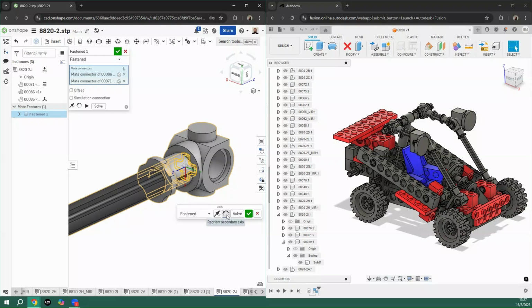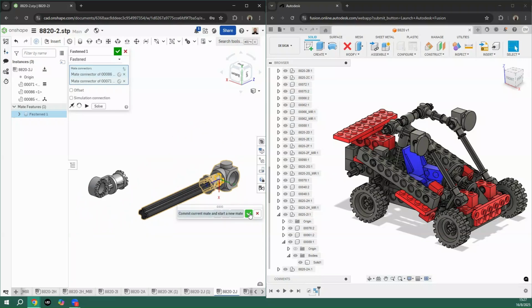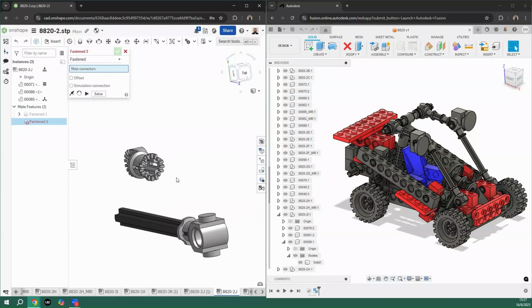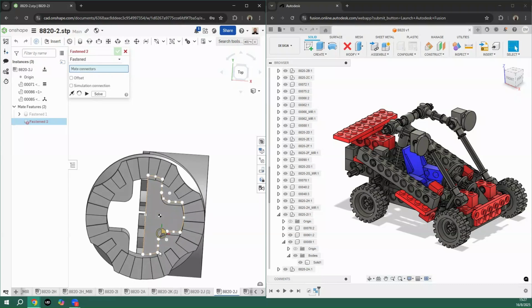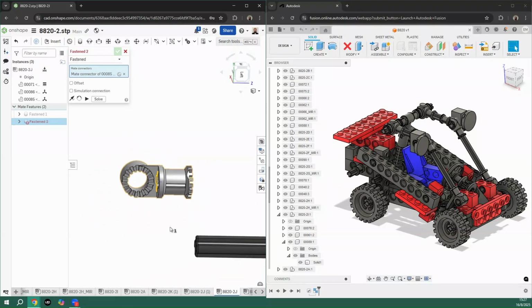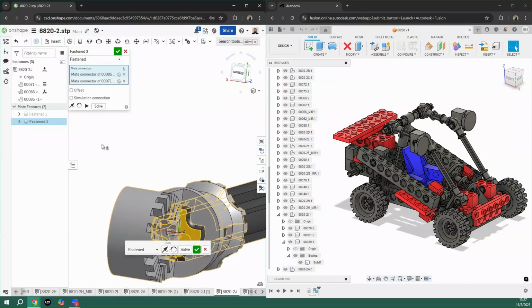We can use this option here for reorienting the secondary axis, so you can flip the part. In our case, that's the correct position that we want. Okay, I will click in here. And now we are going to do the same thing, but in this one. As this has been drawn symmetrically, I can take that point on this part and this other point on this other one.